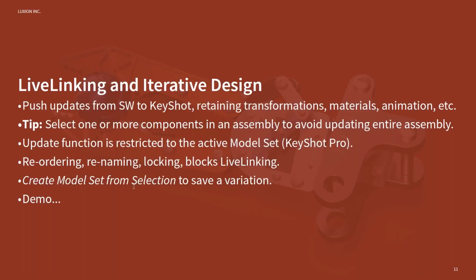And then in the demo, I'm going to show you how to use the create model set from selection command to save a variation of your design so you can have multiple variations in one scene.